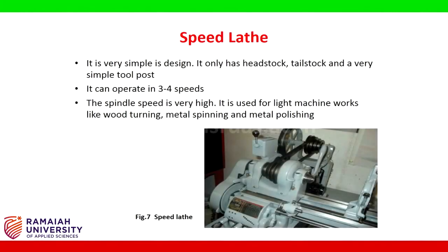Speed lathe. It is very simple in design. It only has a headstock, tailstock, and a very simple tool post. It can operate in 3 to 4 speeds. The spindle speed is very high. It is used for light machine work like wood turning, metal spinning, and metal polishing.